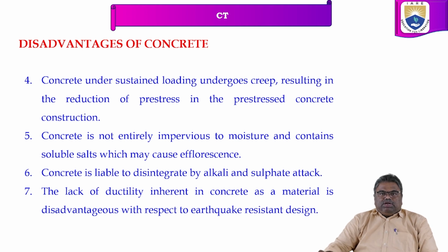And the last one is lack of ductility. The lack of ductility inherent in concrete as a material is disadvantageous with respect to earthquake resistant design. But we can take some measures to achieve earthquake resistant design, though the major disadvantage will be there in case of concrete.